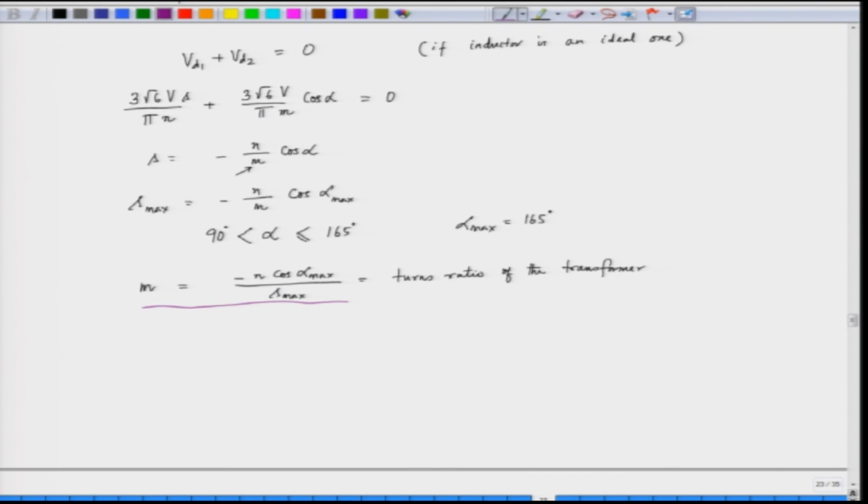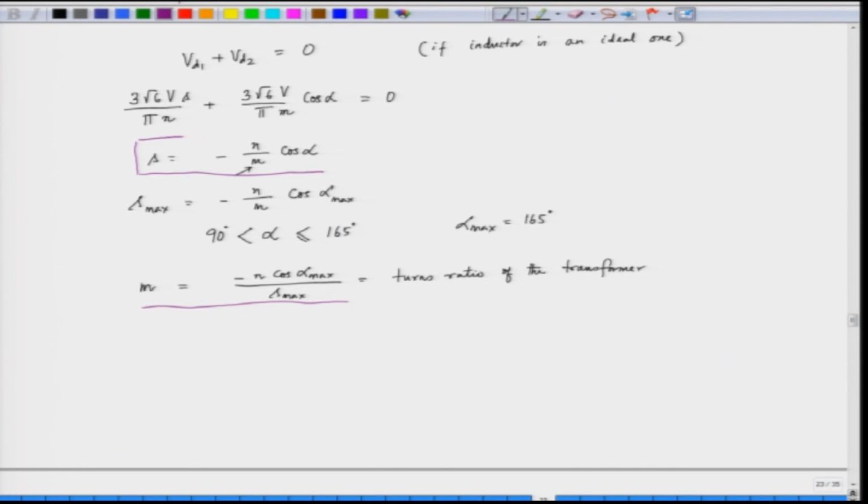So, we conclude here by observing that we can vary the speed of the induction motor by controlling alpha. So, this is our equation which shows that the slip of the induction motor can be controlled by controlling the triggering angle alpha of the converter. So, as we go on varying the triggering angle alpha, the slip can be controlled, and slip has to be between 0 and 1, and hence it operates in the sub synchronous speed, or speed below the synchronous speed. So, we stop here for today's lecture. We will continue with the slip power recovery scheme in the next lecture.